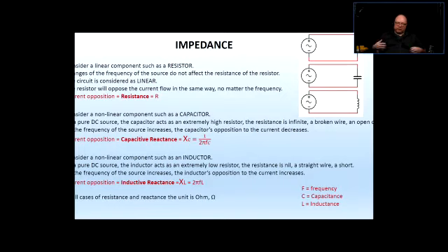Okay? So can we call it resistance? Well, technically you could call this a resistance. But to distinguish that from the linear type of resistance, we're just going to let the resistor keep its resistance, and we're going to call the resistance of a capacitor a reactive resistance, right? Because the capacitor is going to react with its opposition to the amount of frequency that you apply to it. So it reacts. The higher the frequency, less opposition.